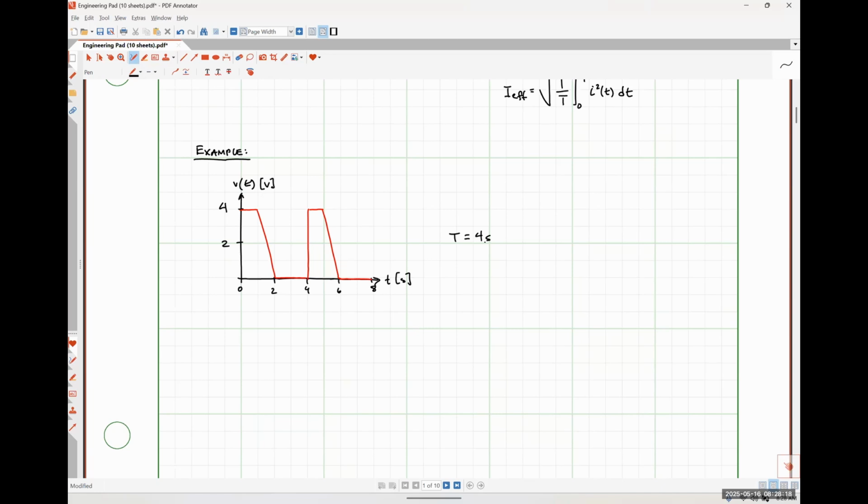So if I were to try to mathematically describe this signal over one period, this is going to be a piecewise function, right? Because it's got 3 distinct things. So to me, this looks like it has a value of just exactly 4 volts over the interval from 0 is less than t is less than 1. For that second interval, from 1 is less than t is less than 2, it has a slope of -4, which has units of volts per second.